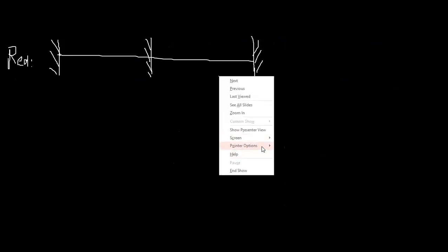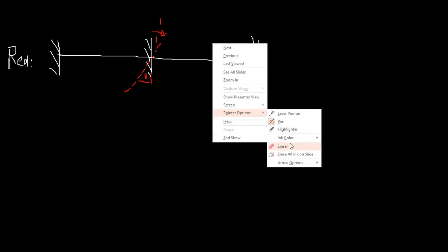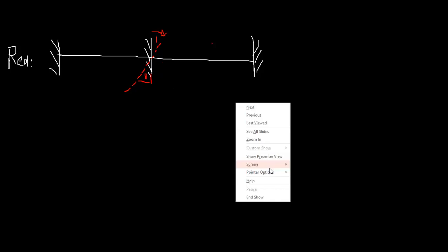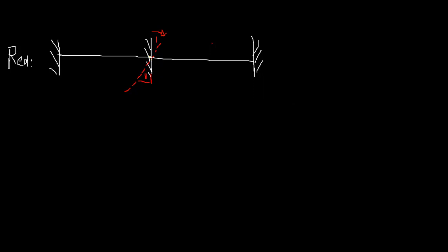So how do I apply that is, I need to apply a unit rotation in the clockwise direction. So theta is 1, okay? Theta is 1. So if you apply like this, your beam will be perpendicular to the fixed support, right? So you are rotating the fixed support, because you know at the fixed support rotations are 0. So the only possible rotation is when you rotate the support, right?